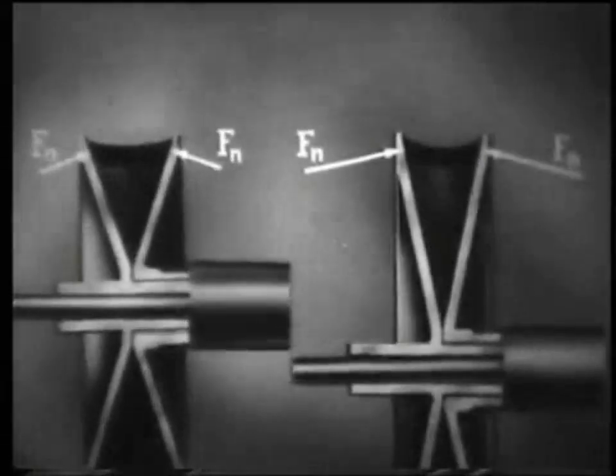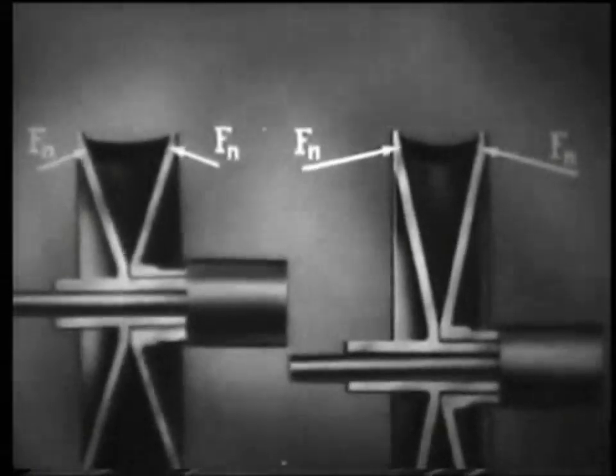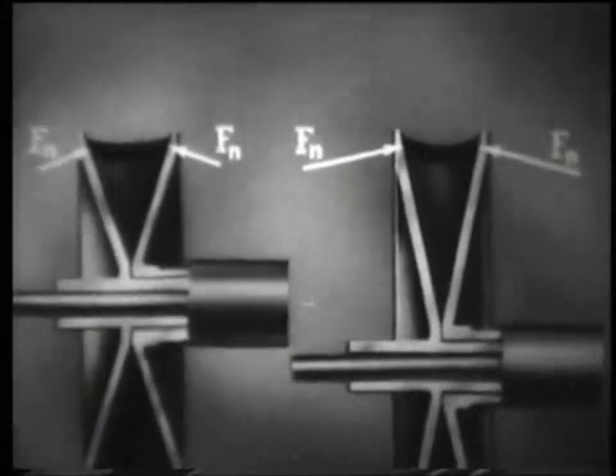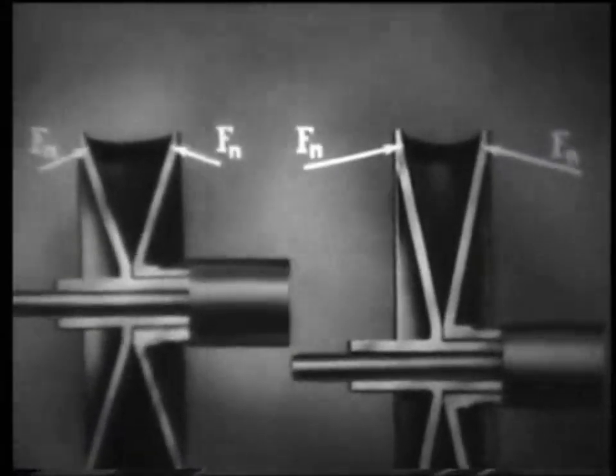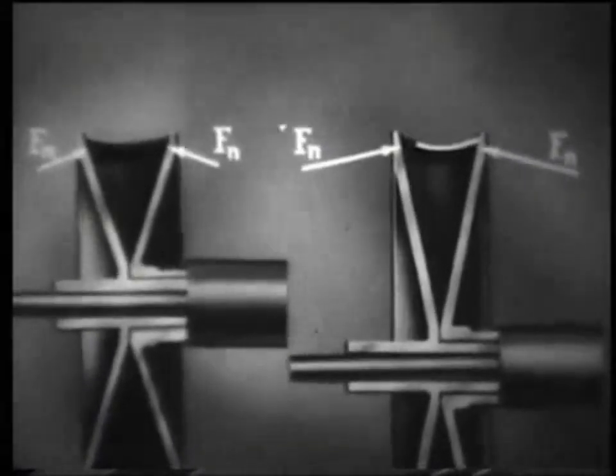For example, reducing the groove angle with the same belt tension increases the normal force compressing the wide belt. The belt deflection in the groove increases. To increase the rigidity of the stretch and compression zone, several layers of fabric are introduced across the belt.